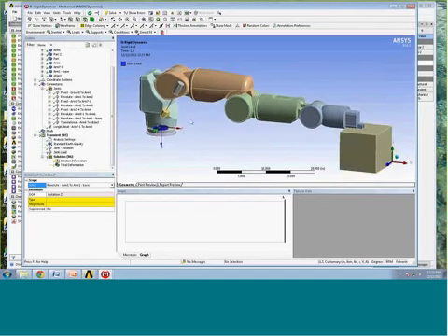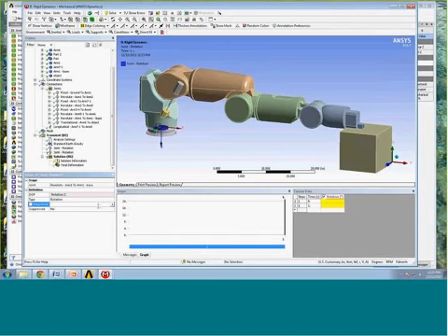I could also apply rotational velocity loads, rotational accelerations, or moment loads. Now the magnitude, I want this to be a nice smooth curve, actually a quarter sine wave type of curve. So I'm just going to cut and paste this functional load. So I change the type of load to a function. And you'll see it's going to rotate from 0 to negative 45 degrees.